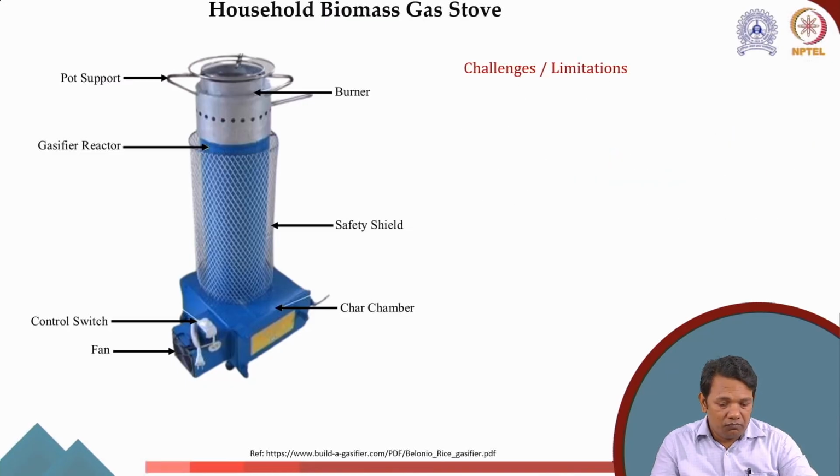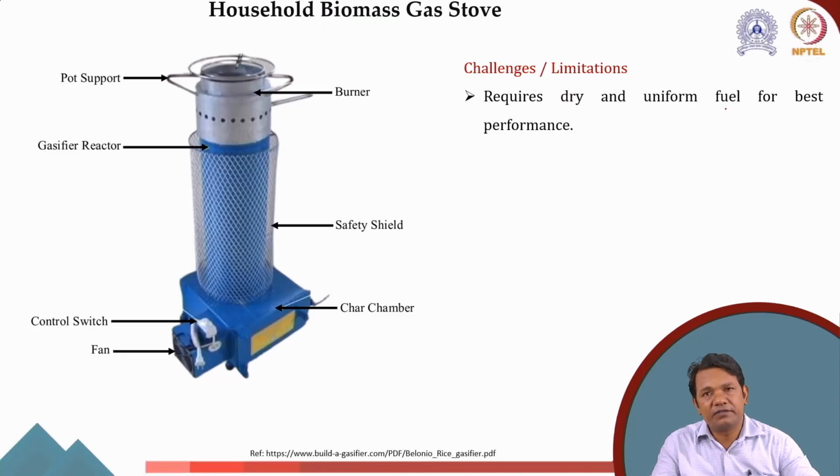Now, having said so many advantages, it also has some limitations. For example, it requires dry and uniform fuel for best performance. Okay. Now, drying itself is a challenging task. If you go for natural drying, it will take days, while if you try to dry the feedstock using a commercial dryer, then it will require a lot of energy.